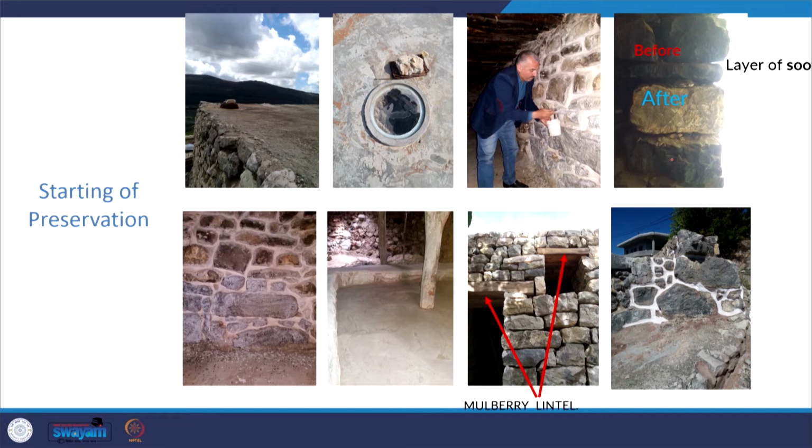So what they did was, Geet applied the lime coating for 2 days, and after that, every day twice, washed with water for 20 days. And then he waited, let it dry for another 20 days, total 40 days. And this is what the result is, before and after. So the whole soot has disappeared, and he completely washed it with the lime water and the normal water wash.